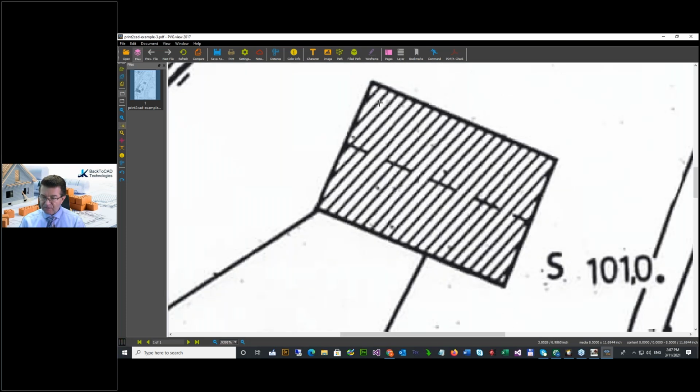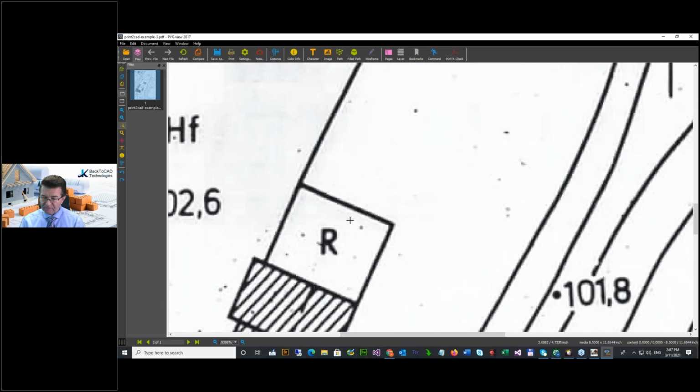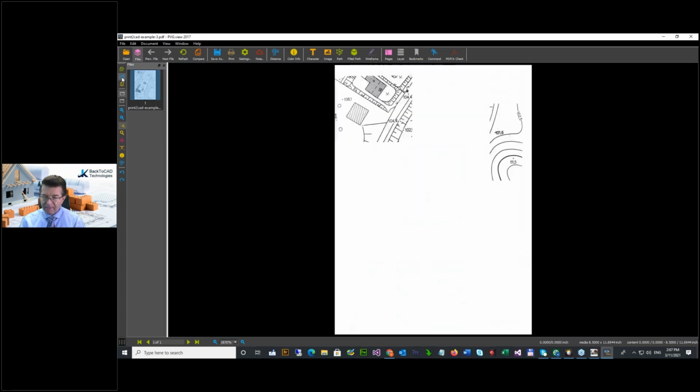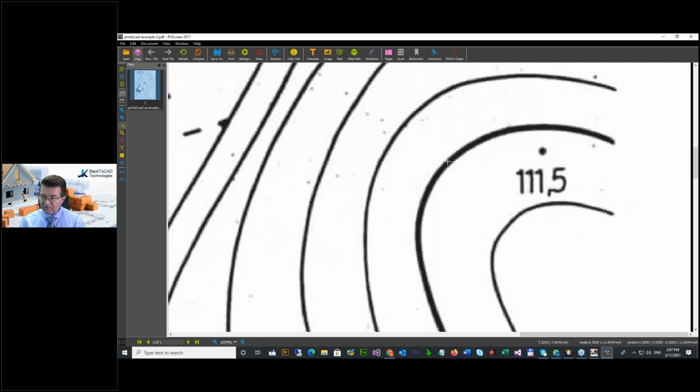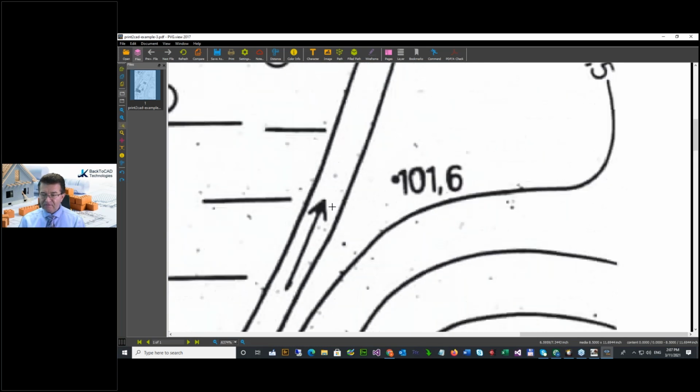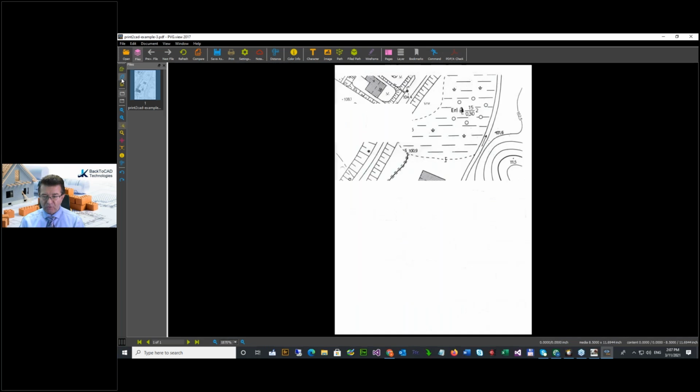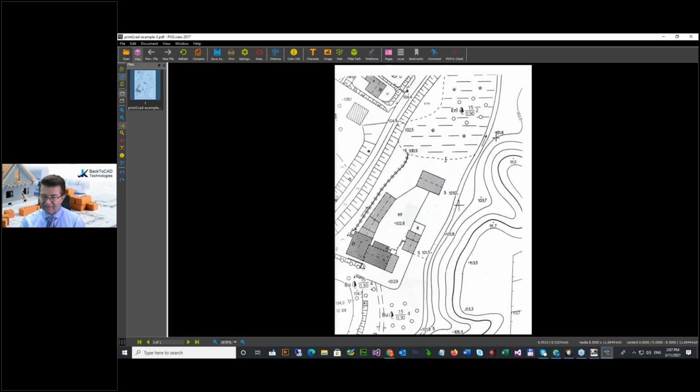In this building, you expect that you recognize the right corner as a straight line. But here you expect that we recognize maybe the curves. This is something you have to decide, because you can't activate curves for this part and right corners for this part. You can set parameters only for the full drawing.